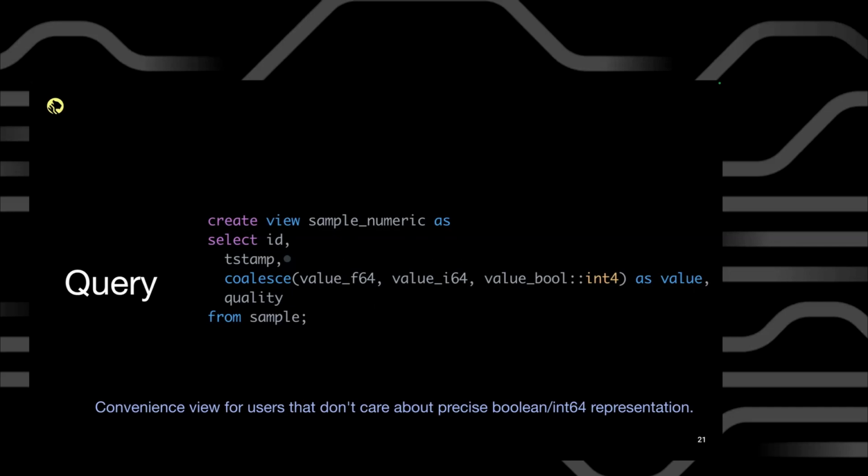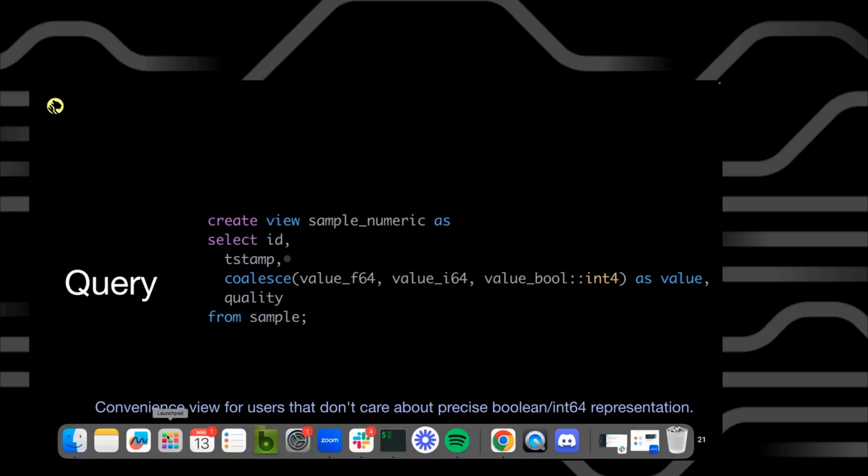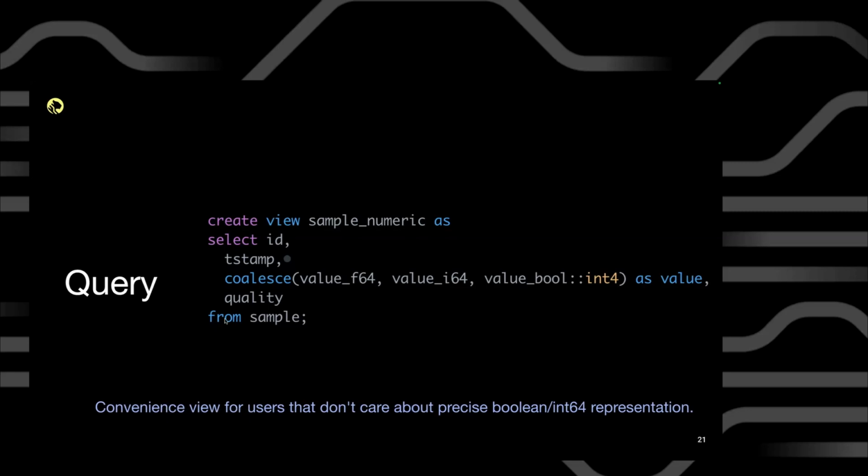And there was a question to close. There was a question in the chat that says, "What kind of protocols do people use between the sensor and the database?" In the case of oil and gas, industrial protocols are quite common. So you have OPC, OPC DA, OPC UA, and variations by vendors. Vendors add extensions to these protocols to handle specific cases of various installations and controllers in the field. So you need a special gateway that knows all these protocols.